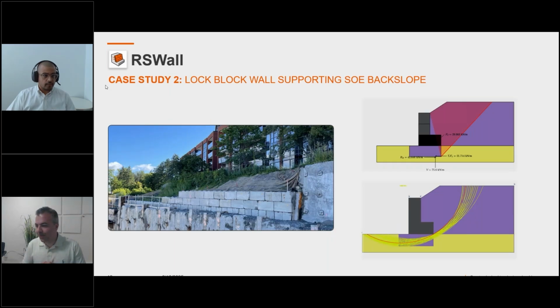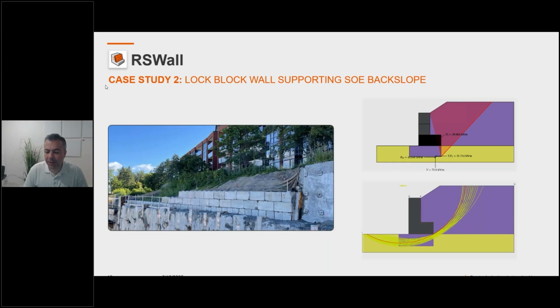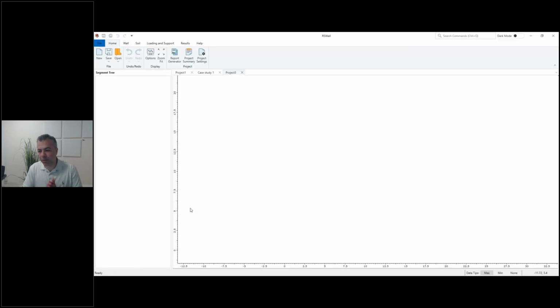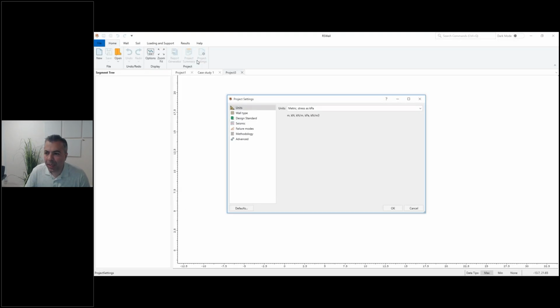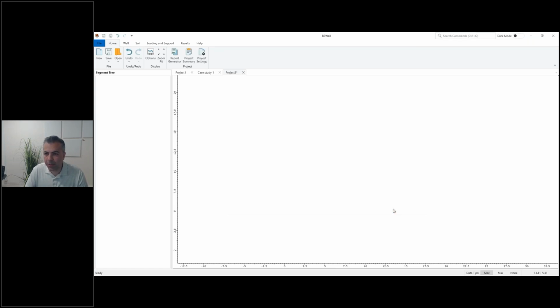Thank you, Ali. It was a nice case study. So I'm gonna create the second case study in RSWall. So it's the lock block wall, and let's see how we can do it in RSWall. So I'm gonna start with an empty project. In the design standard part, we are only interested in the serviceability for this wall. So I'm going to just pick the serviceability option. And also, as Ali explained, we are not interested in the internal stability of the wall. We are only interested in the external stability of this block wall. So with that, I hit OK.